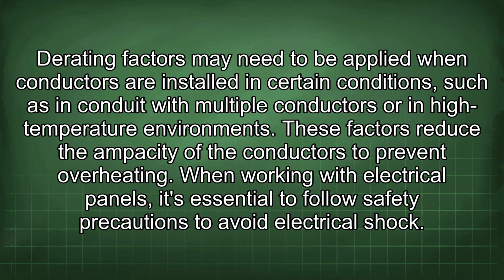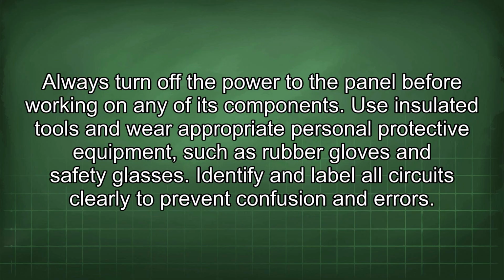When working with electrical panels, it's essential to follow safety precautions to avoid electrical shock. Always turn off the power to the panel before working on any of its components. Use insulated tools and wear appropriate personal protective equipment such as rubber gloves and safety glasses. Identify and label all circuits clearly to prevent confusion and errors.